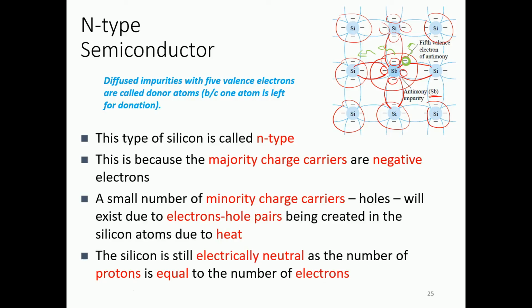So this is how the doping is happening, or this is how we are creating an n-type material. And you can see the negative charges, or the electrons, are in greater quantity, so we are calling it an n-type material. So again, to summarize, whenever we have pure silicon, and if we bring another element from the outside that has more valence electrons than silicon, we say that we have created an n-type semiconductor, and this free electron is now able to move here and there, and it can be used for conduction. In n-type material, the majority carriers are negative, or electrons, and obviously the minority carriers will be holes.